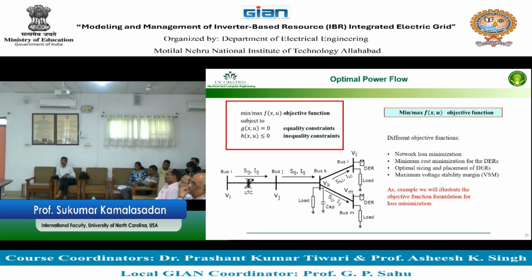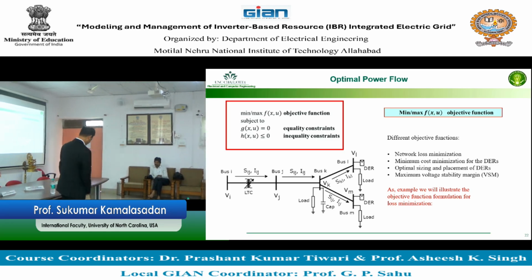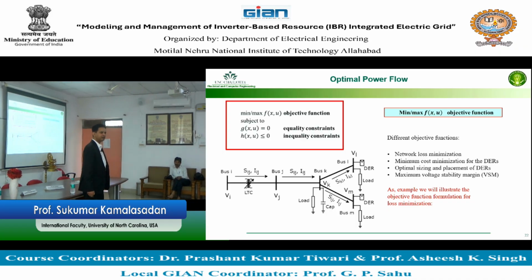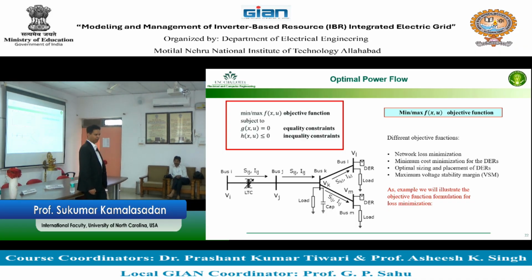So there is a very interesting question. Optimal placement is an optimization problem. What optimal placement gives you is the best place to locate a device in an electric grid, considering the voltage and what you want to do with the device, like maximum power. For example, for DER, your best location will be where your voltage is very strong, not changing a lot, so you can get maximum power from the DER. That is basically the optimal location problem.